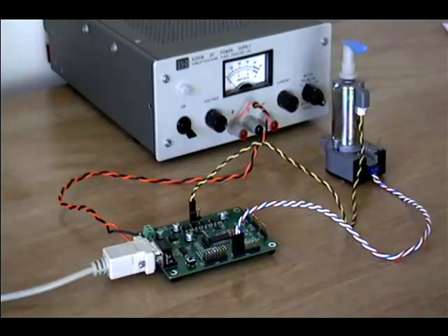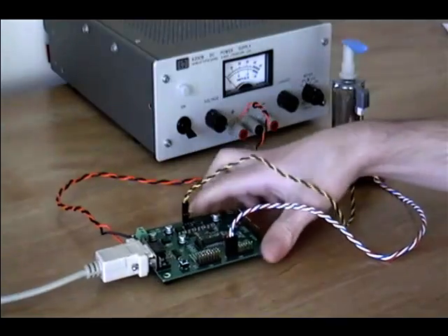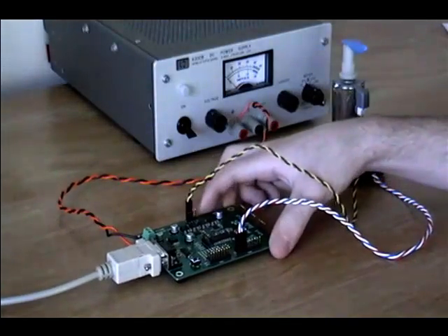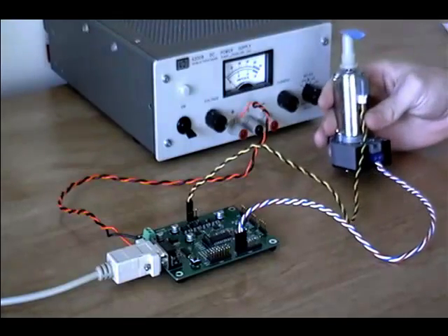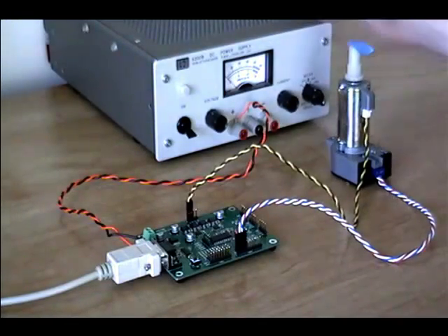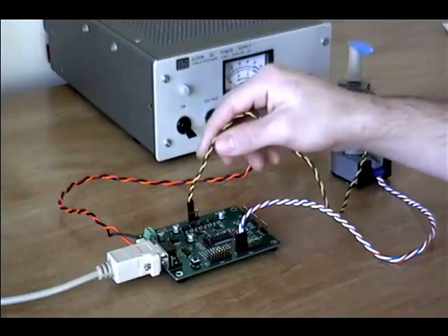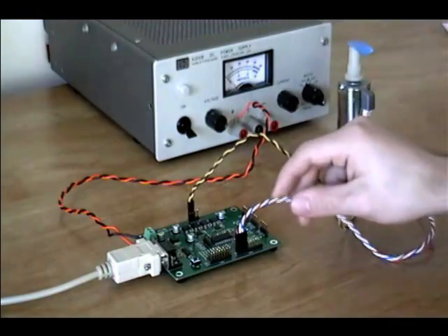This is a brief demonstration of how you can control a DC motor with our Simulink platform. First, the hardware setup. Here we have our control board, which is connected to our PC running Matlab. Here we have our DC motor with embedded encoder, and our power supply. Our DC motor is connected to one of our H bridges, and our encoder is connected to one of our encoder inputs.